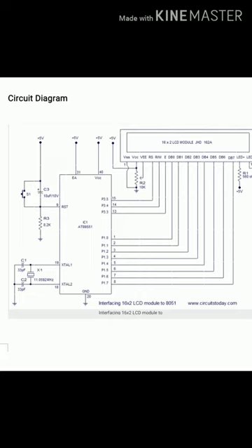Coming on to P3.4, you can observe that it is connected to the R/W signal, read bar write signal, and this has to be all the time 0. Therefore, when you send 0 on this particular line, it says that the microcontroller is writing the data through port 1 into the lines DB0 to DB7. So DB0 to DB7 will only accept the data. Port 1.0 to port 1.7 will only send the data. Other way is not possible, right?